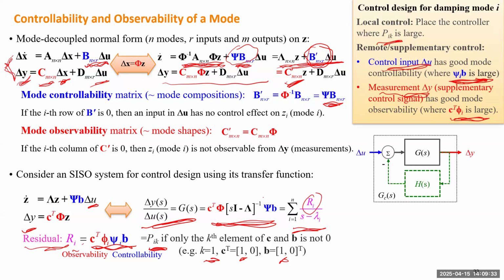All right. So when I collect the remote signal and send it back to the controller, I can design a transfer function as feedback control. If I am able to design this H, I can design the target eigenvalue, including how I want the frequency to shape and how I want the damping to be improved, because the closed loop transfer function will be this one. The G here is the original transfer function from that input to that output of the original system.